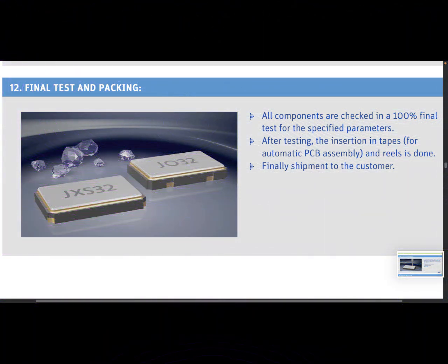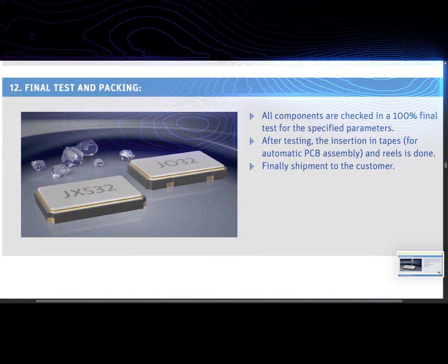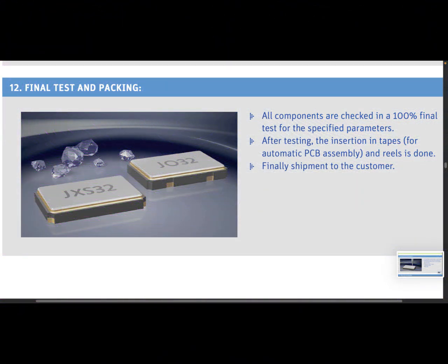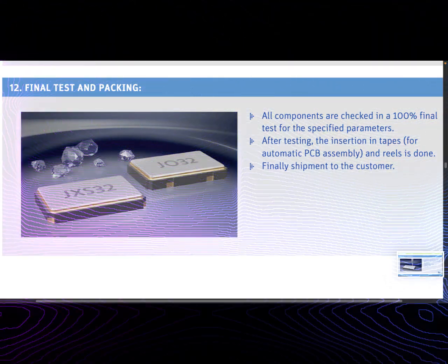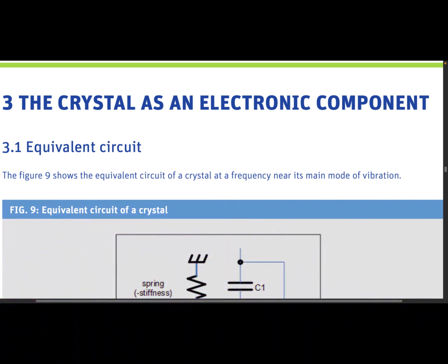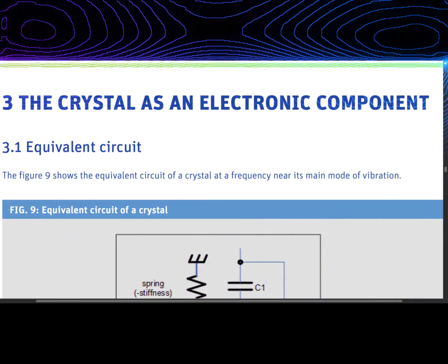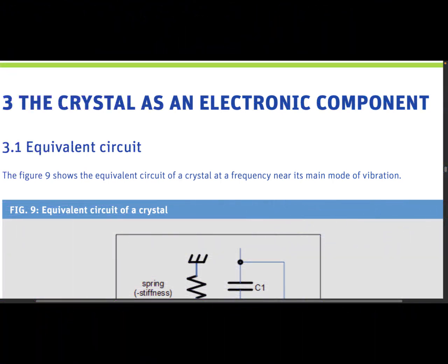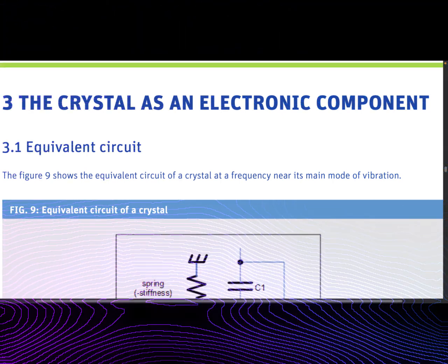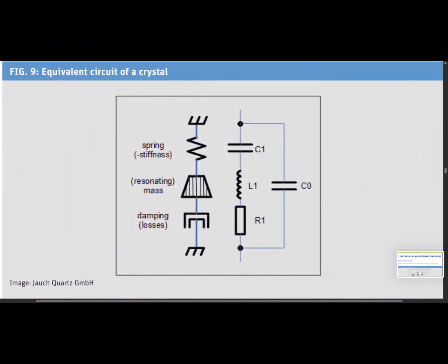In conclusion, RC oscillators are simple, but do not provide the accuracy and stability required by many applications. Those requirements can be met using a crystal oscillator. Designing an oscillator from scratch can be complicated, but you can often use the oscillator built into the device that requires the clock.